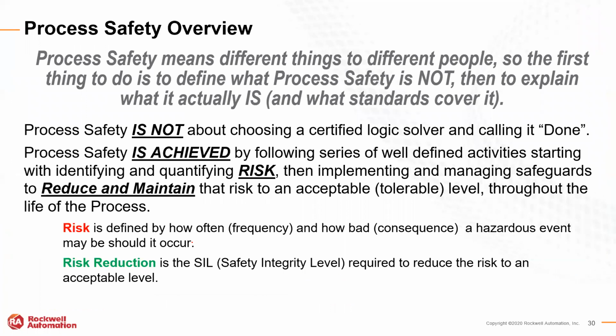So what is process safety? You had a good overview of machine safety from Eric, and we want to just show where this differs a little bit. Process safety is not about choosing a certified logic solver and calling it a day. It is achieved by following a series of well-defined activities, starting with the identification and quantification of the risk. So what is the frequency or the likelihood of that risk? And then what is the consequence, or how bad that risk is going to be?